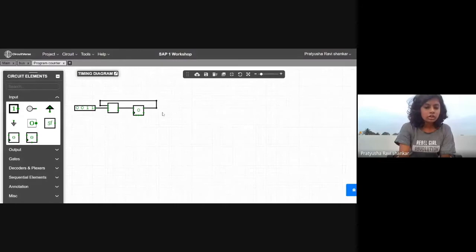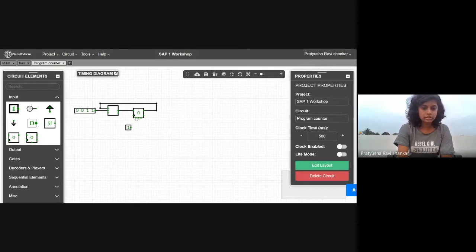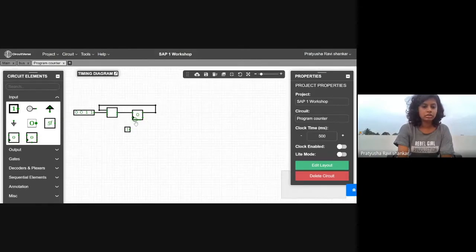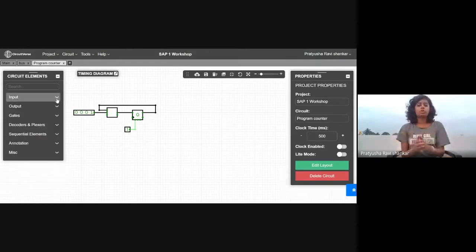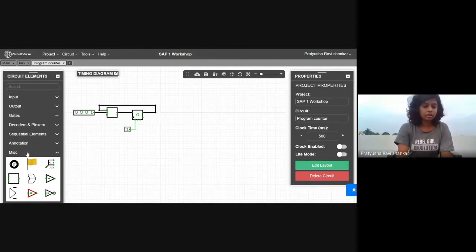So that is there, and we'll set our control bits. So this is to enable the register. Cool. And this was set to 0. And again, to control when the output of this program counter should be and should not be on the bus, obviously we have to use a tri-state register.